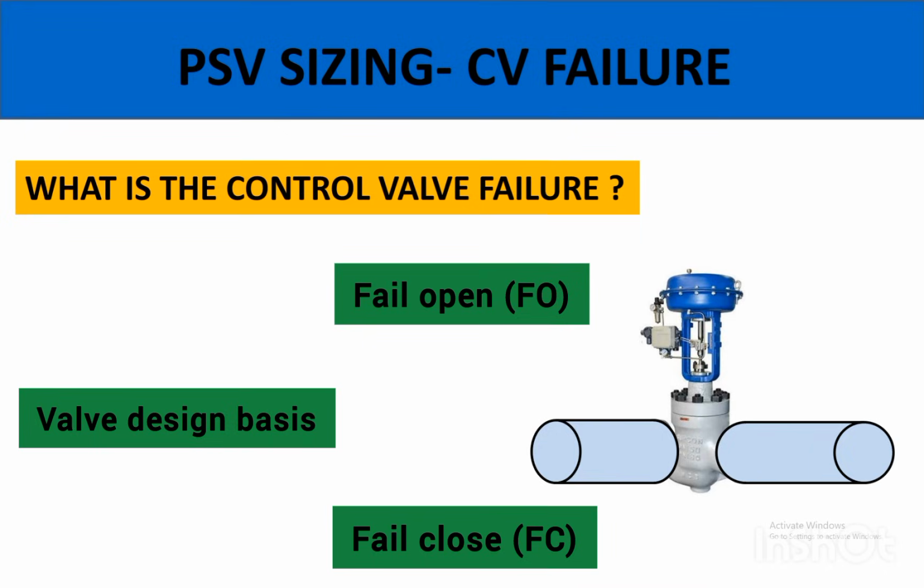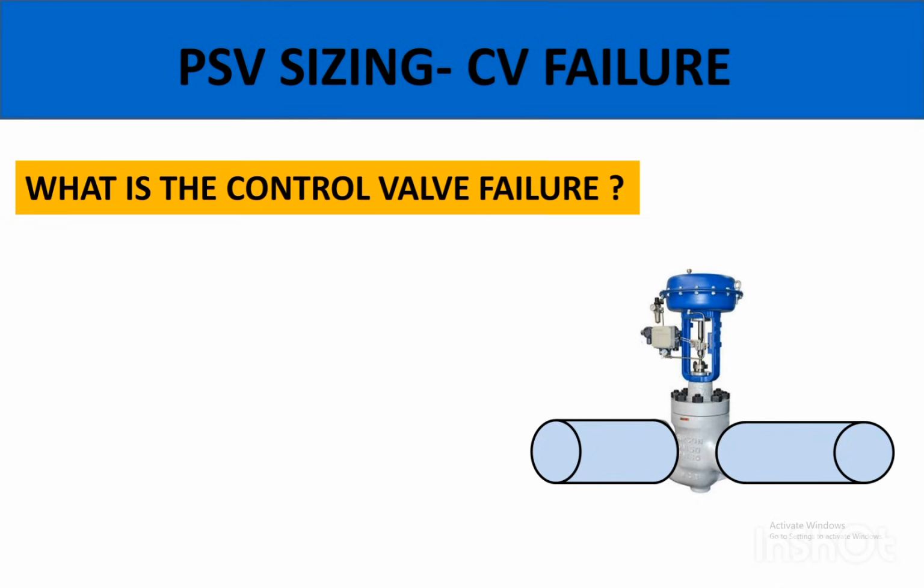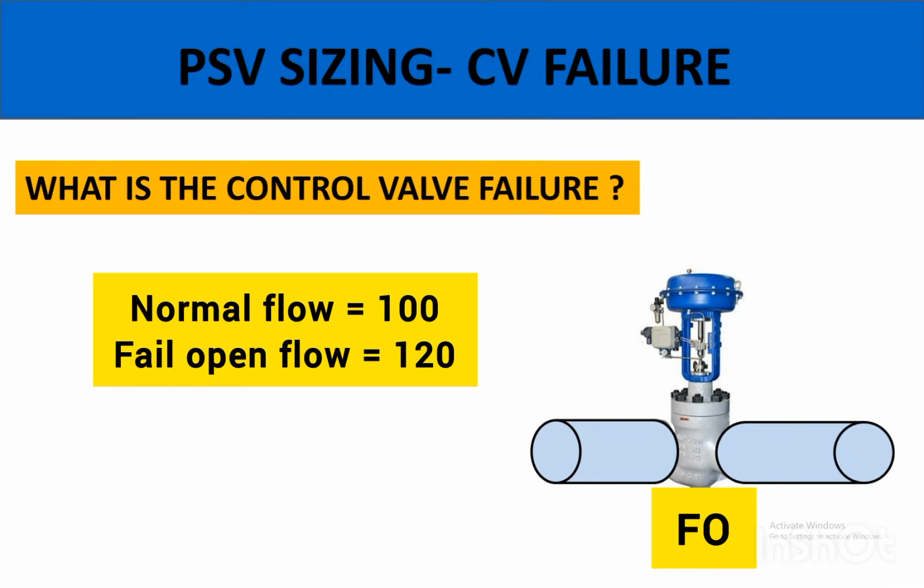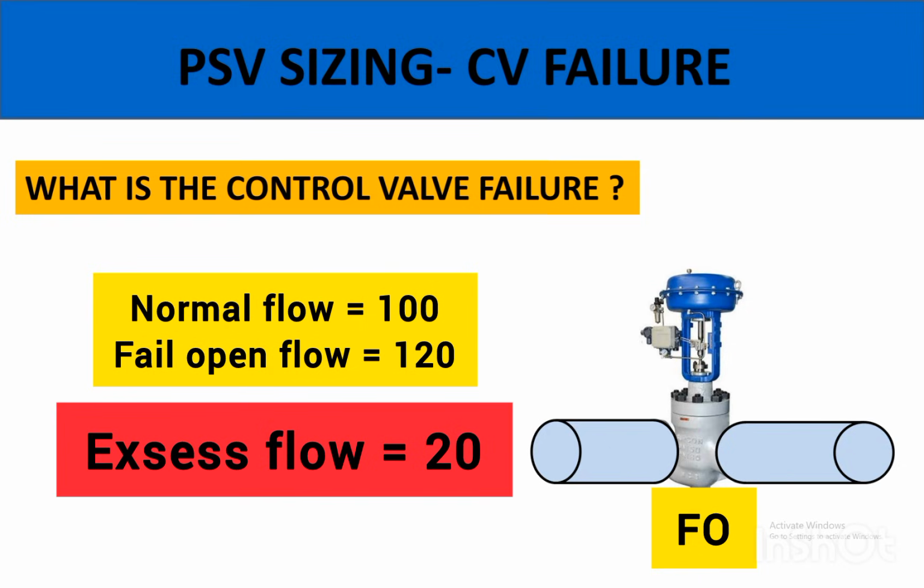What really matters is that this valve has failed, and it's considered that this valve is open, that the valve's opening is 100%, and this valve actually passes more flow rate than we expected. So we should consider what we want to do with those unintended flow rates or unintended pressure that may be encountered when the valve is fully open. As you know, valves operate within a range of 20 up to 80% opening, right?